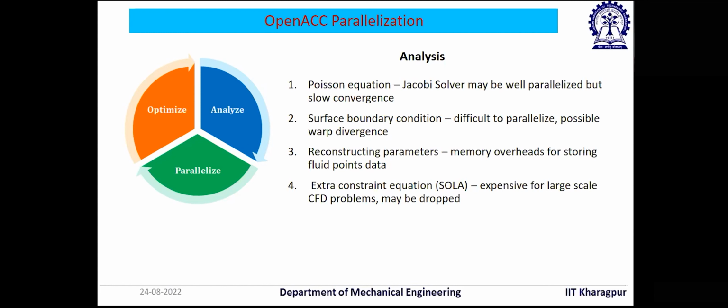Compared to a general successive over-relaxation solver or a matrix vector product based solver like Krylov subspace solvers, the Jacobi solver can be very easily parallelized. We can work with a smaller amount of memory. We can consider the diagonal nature of the matrix, and it's completely explicit. However, it has a very slow convergence rate.